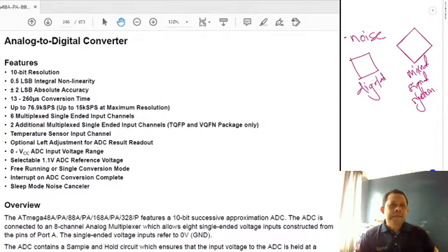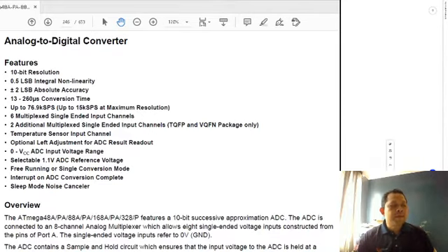So if you have the ADC embedded inside your single chip microprocessor, the disadvantage is that the developer or the engineer has to accept the level of noise that comes together in one package.